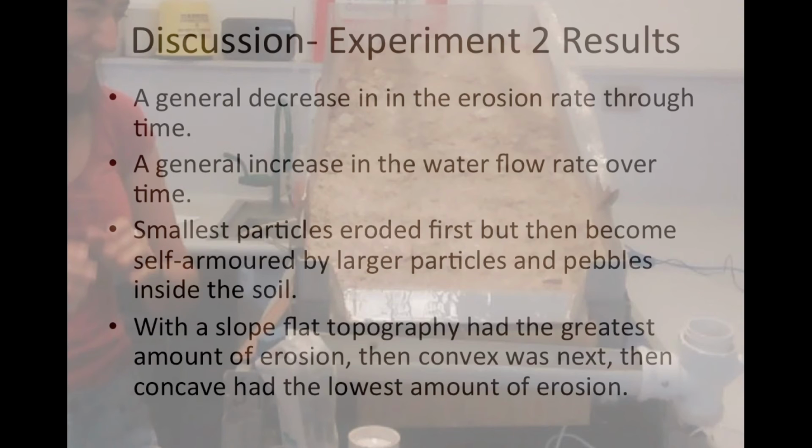Because the soil was very clay-rich, clay particles could have formed electrostatic forces between each other and hence made aggregates. These aggregates need a relatively high velocity to break up the particles from each other after all the less compacted sediments are washed away. This could also explain the decreasing trend seen in the erosion rate through time.